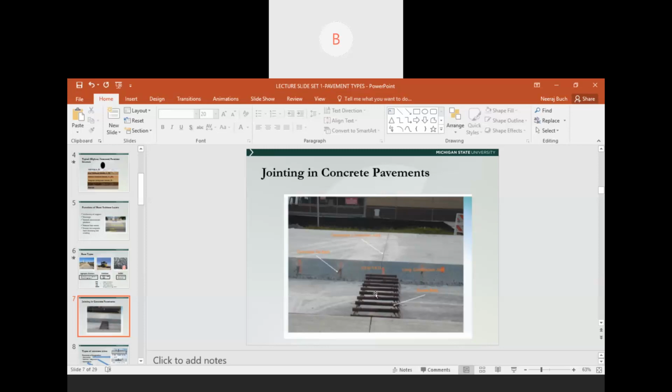That will not work, because the functions and the physical characteristics of these two bars are quite different. So you cannot interchange a dowel bar with a tie bar and hope to get the same performance, because you will not, because they're designed to carry out specific actions in a concrete pavement. So the differences between these two need to be noted.